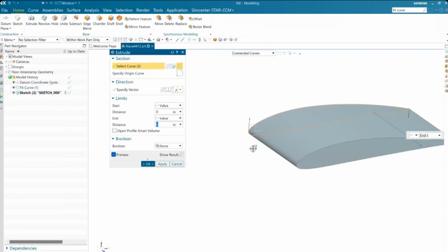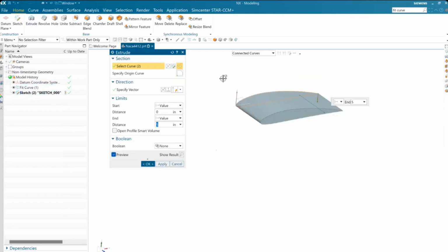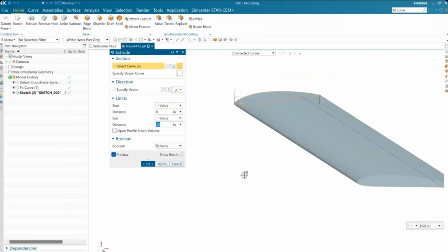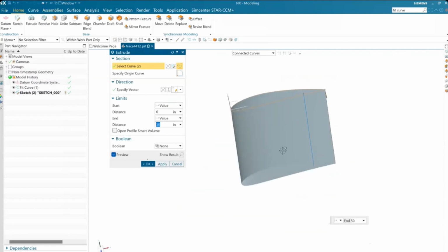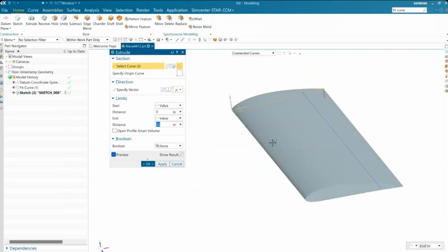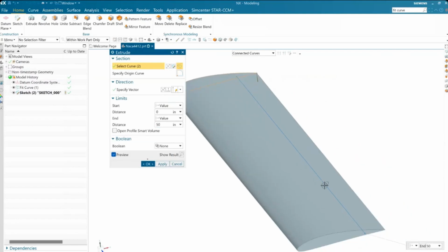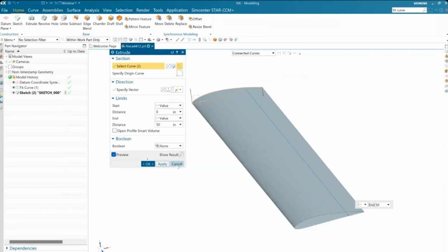Eventually, you have an airfoil. Now, one of the common problems in NX with this method is if you choose a really large chord in Airfoil Plotter, you can have the viewing be very weird. So like this, let's say I put 50 in here. The viewing gets really weird around here. And this can happen with points. Your points will fade in and out, and it'll be really weird. So right click, Fit, solves all the problems with viewing.